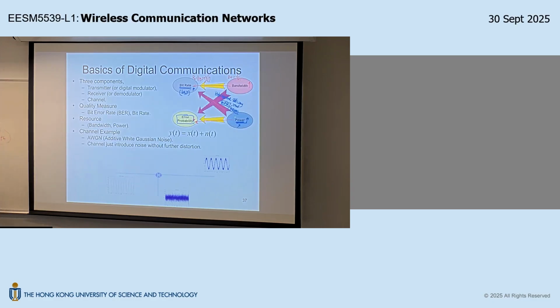But for 16 QAM, if the baseband is sending you a 16 QAM signal, although your maximum transmit power is 30 dBm, you need to back off by 10 dB. So your transmit power is only 20 dBm. You understand what I mean? So for the same physical power amplifier, transmitting 16 PSK, you can boost up the higher output power, 28 dBm. But for 16 QAM, you have to scale down your transmit power. You can only transmit 20 dBm.